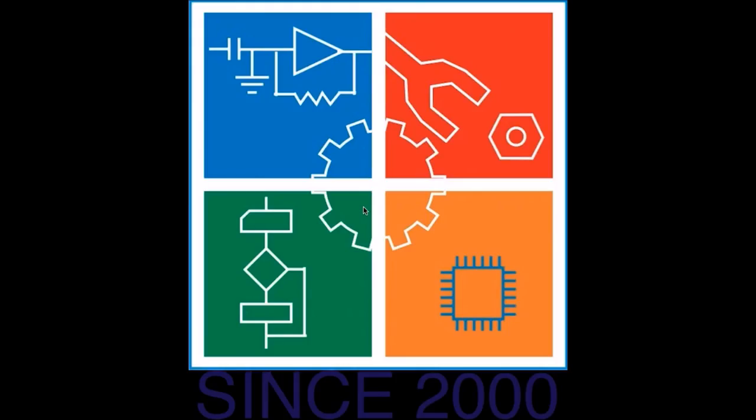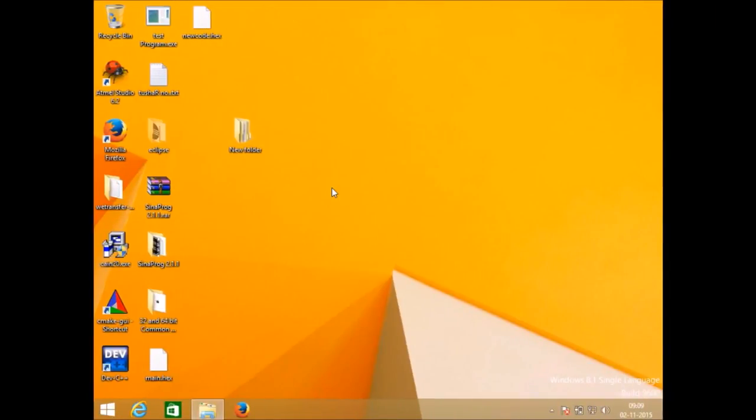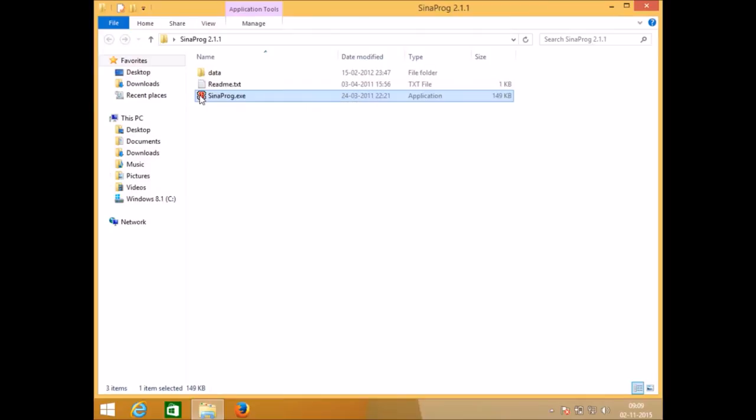I am Rajiv and in this tutorial we are going to learn how to set fuse bits of your microcontroller using sinaprog. So to start with you must have sinaprog. Open the folder and run sinaprog.